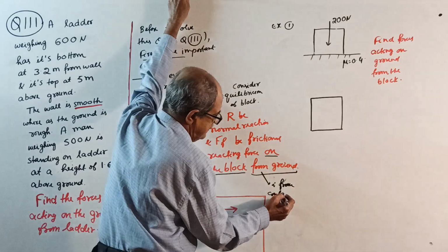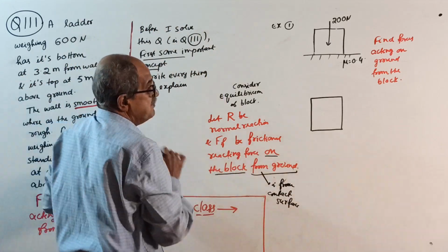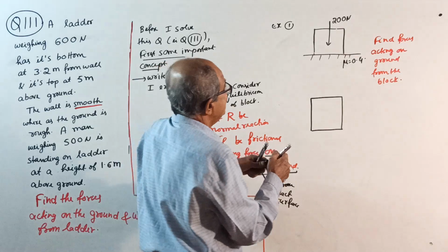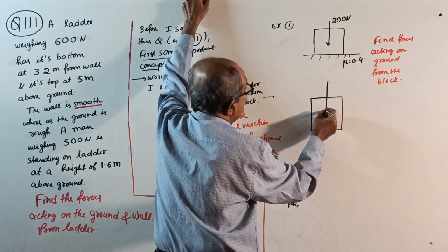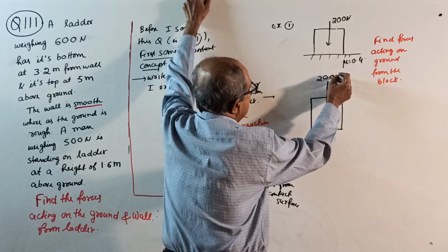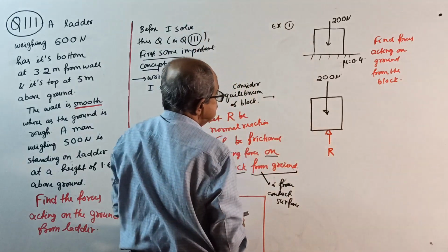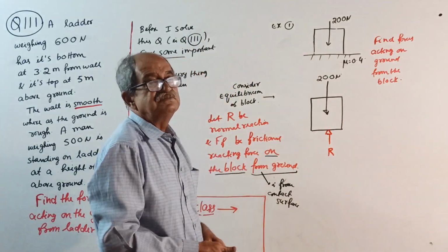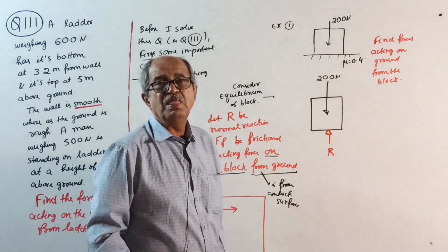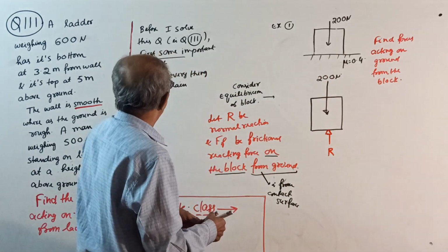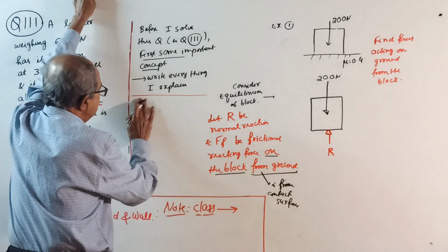or to make it more clear, from the contact surface. Why am I telling contact surface? Because this question has got two contact surfaces. So mark here. Now write, consider free body. Weight W acting, this is called action, 200 Newton. There is a normal reaction R on the block. Then which side is friction? There is no question of moving. They told friction is 0.4. Make a small note somewhere outside, separately write, note.